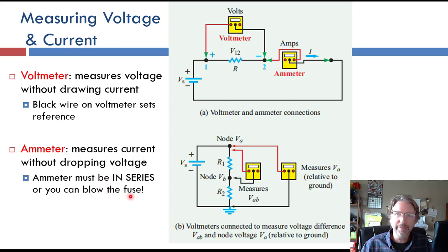So it's very common in things like makerspaces, where you can borrow voltmeters, that the fuse is blown from people hooking up the current measurement wrong. So make sure it's in series. You'll get to practice this in the circuits lab.